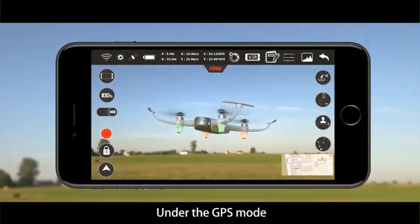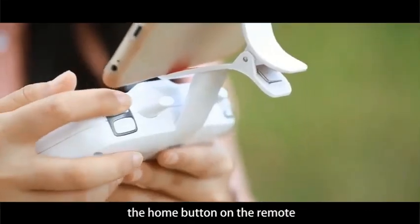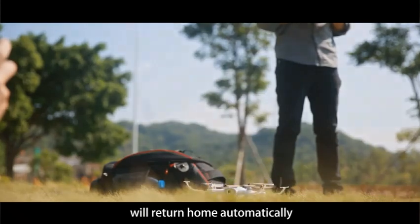Under the GPS mode, when the aircraft is out of view, you can slide or long press the home button on the remote for returning. When the battery of the aircraft is low or the signal is lost, the aircraft will return home automatically.